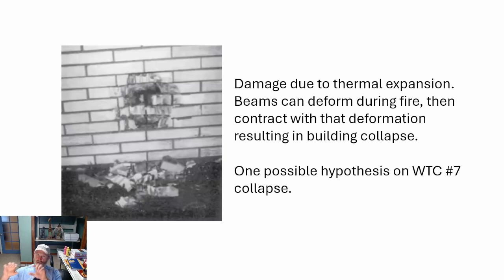So what you had is those I-beams that connected the center concrete area to the exoskeleton. They expanded because of the intense heat. And because it expanded against that exoskeleton, it bulged a little bit. And that created that eccentric loading that resulted in it collapsing. Because it doesn't take a lot of force. When you have the eccentric load, it doesn't take a lot of force to collapse a column. And that's effectively what happened there.